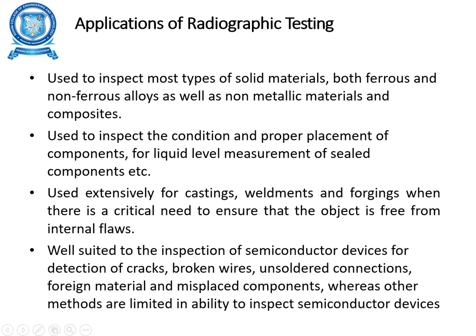Coming to the applications of radiography testing, it is used to inspect most types of solid materials, both ferrous and non-ferrous alloys, as well as non-metallic materials and composites. It inspects the condition and proper placement of components, and liquid level measurement of sealed components.